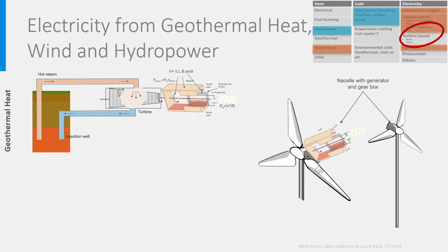system. However, there are many other locations in the world where the ground temperature is much lower than 100 degrees, making it impossible to make steam with a pressure high enough to drive the turbine. This problem can be solved by using a closed cycle, using a refrigerant with a boiling temperature lower than the one of water, a so-called organic Rankine cycle.